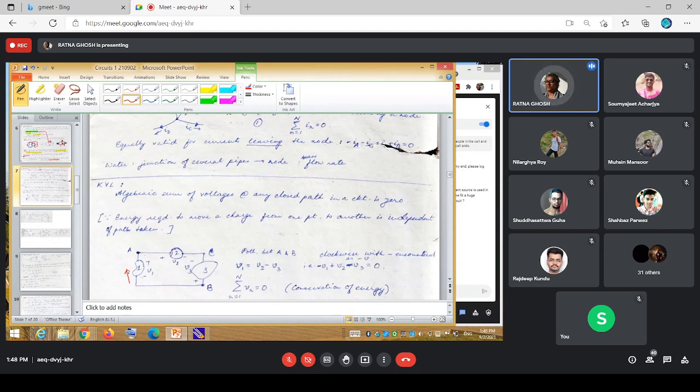It encounters a minus sign here first, and this is the equation which becomes valid then. So it's minus V1. Next, it encounters a plus here, so take that sign up, plus V2. Then it encounters a minus sign here, minus V3, and you're back at this place. So the closed path total is equal to 0. Or in other words, V1 is equal to V2 minus V3.